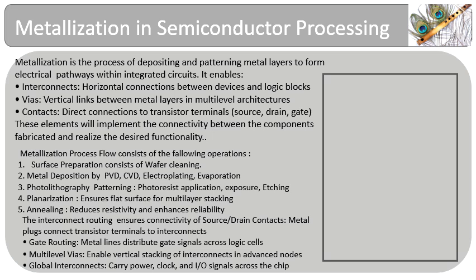Metallization is the process of patterned metal layer deposition to create electrical pathways within integrated circuits. It enables connectivity between devices and logic blocks. It generates vias that connect between vertical metal layers, and contacts to the pins of the transistor. The interconnects created realize the desired electrical functionality.